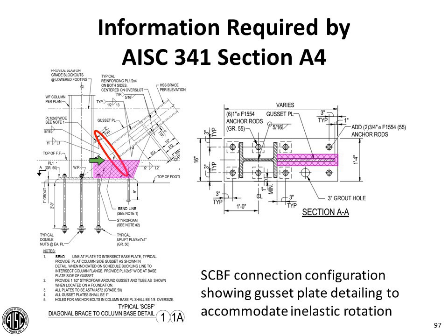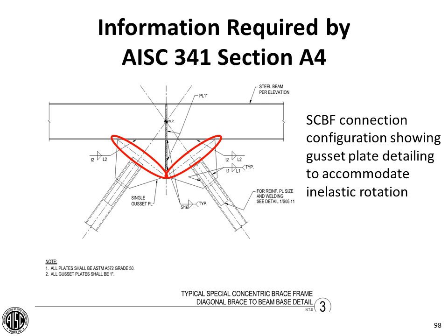If the compressible material had not been provided, this bend line or fold line would not be able to form in the geometry that the engineer of record assumed when they detailed and designed these particular connections. So you can see both in elevation and in plan, in this case I think it was 1.5 inches of compressible material. I think the detail uses the term styrofoam, but that's proprietary, so compressible material is probably a better term, and then that could be defined in your specifications.